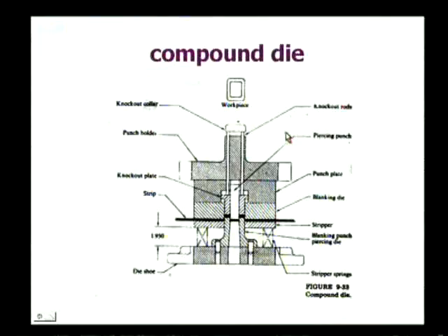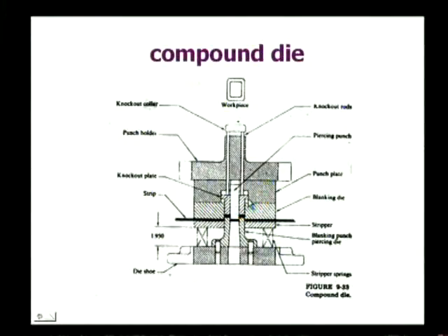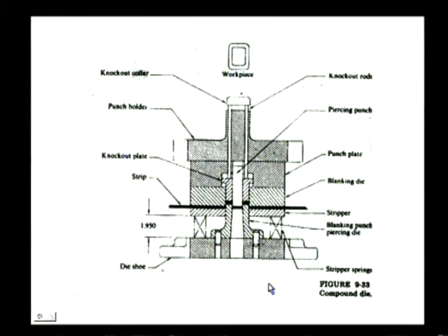So that is the advantage of the compound die, and all the other components of the die can be observed here. These are the springs, and a knockout pin is also required to knock out the material being pressed from the die cavity. Because after cutting it may slightly enlarge and grip in the die cavity unless it is stripped out, so it will not come out. Strippers can also be seen here, enlarged.